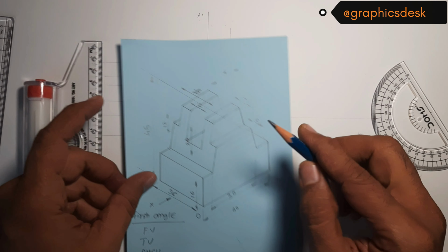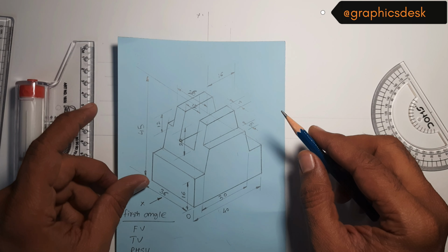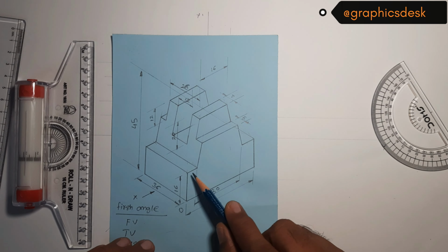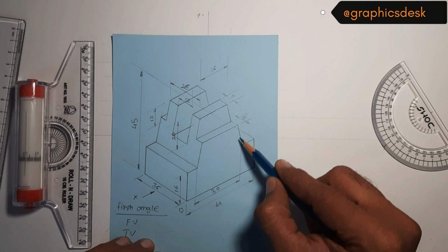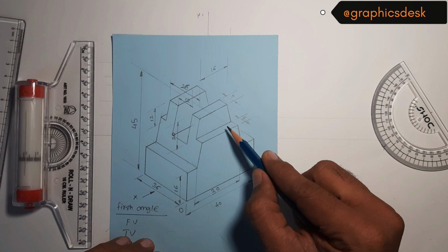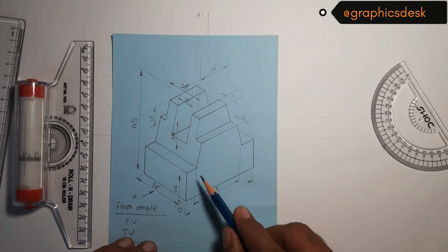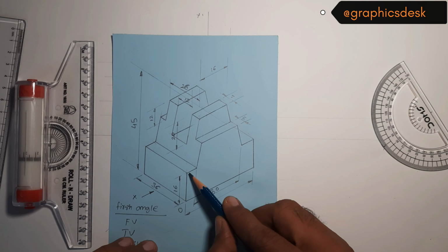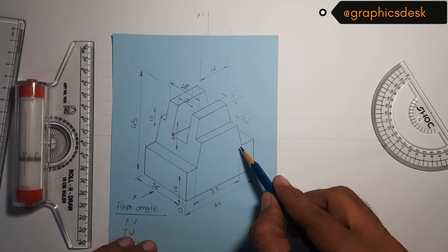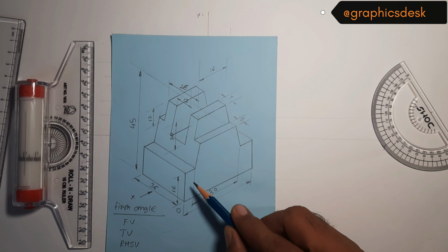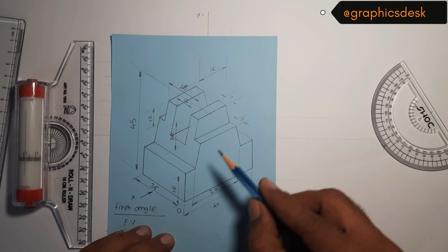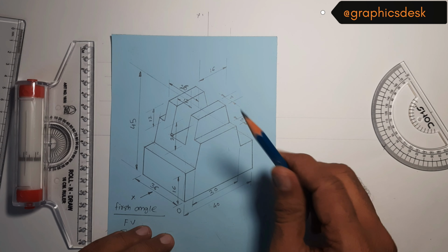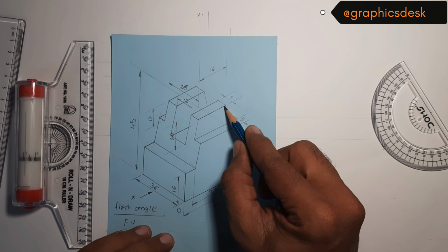Now, our right hand side view would look like a rectangle and then a half triangle or partial triangle on it. So this will be the face which will be visible. So these lines would be solid. The base would definitely be solid. The 16 mm height will be solid, and this is where the line will come from the projection that we have taken, and this is also at the top.